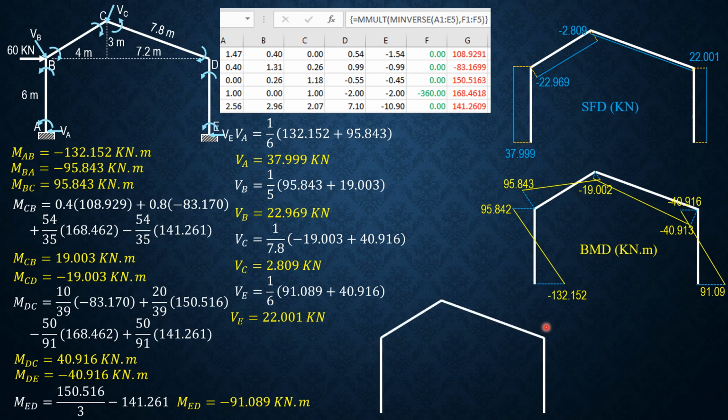Finally, for the elastic curve, so we have concave down if we flipped our view, then concave up here, then concave up, then a little bit down, concave down, then concave up. So that's the approximated elastic curve as shown in the figure, and therefore that's the elastic curve. So that's it for this problem.